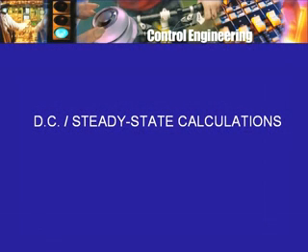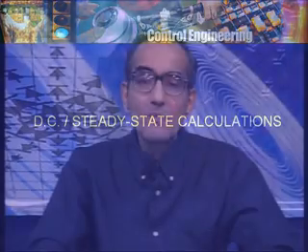So this is the DC or steady state calculation which one can go through, which is necessary to proceed further. Of course, we can stop here. We can say, alright, let us buy the motor, let us get this power supply voltage of 230 volts, arrange for the field winding, maybe a resistance in series with the field winding, whatever arrangement, so that the calculated field current will result.